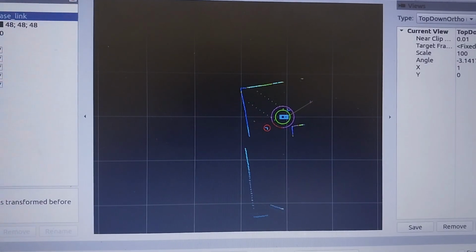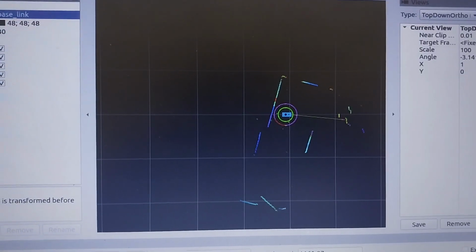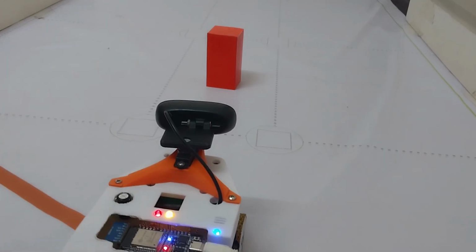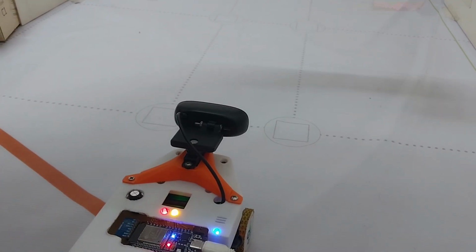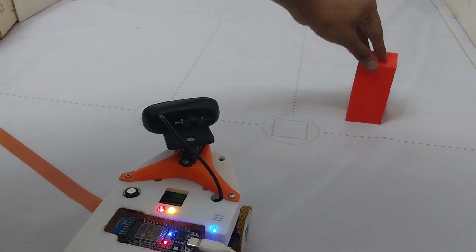To detect the traffic towers, normally you'd use a color matching system using the camera, but there are some problems with that. For example, a lot of times the camera detects the parking spot as red towers because their colors are very similar. So what we did is we used the LiDAR values to match the shape of a tower. We detect the towers using the LiDAR values, and then we use the camera to detect its color. That's not happening for us because their shape is different, and using LiDAR we can detect those shapes.